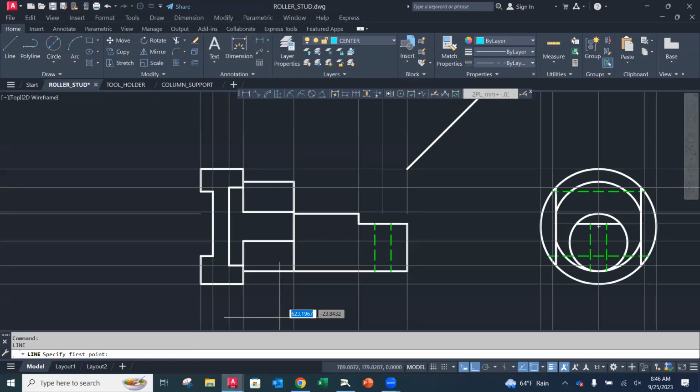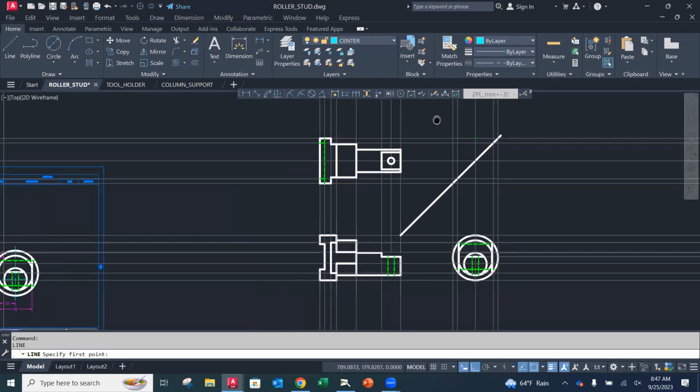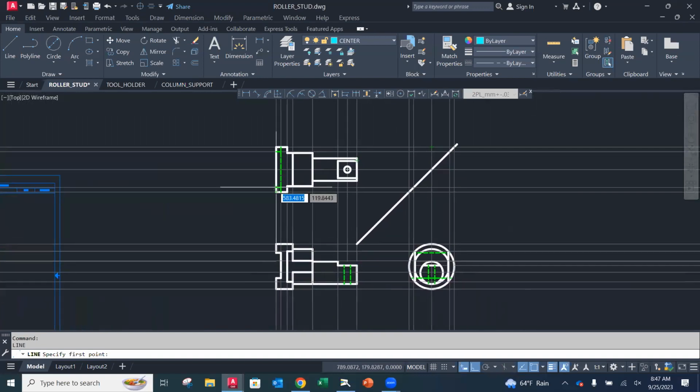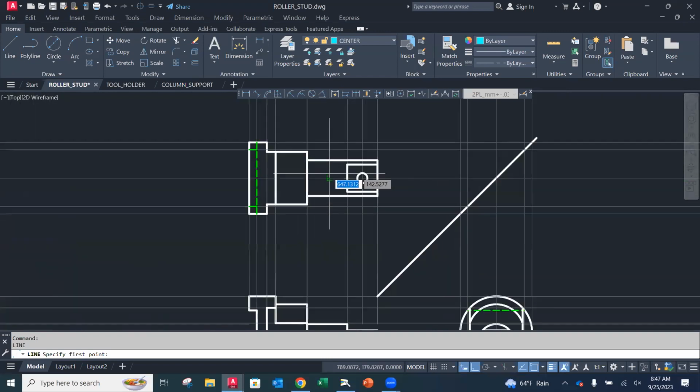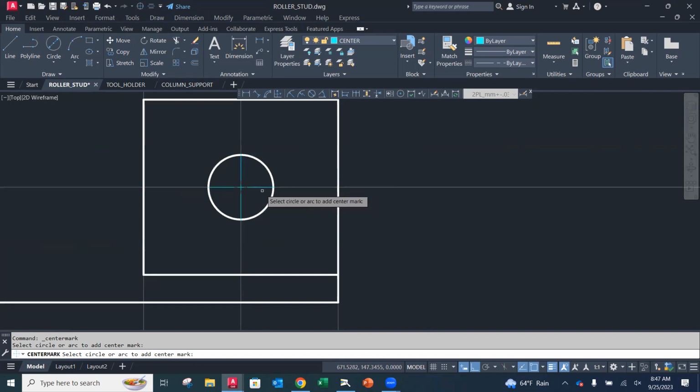All right. So now that we have the construction done, like I said, center lines, I'm going to let you guys put those in. Does that sound okay? Go ahead. Whenever an arrow is dealing with the center mark, it doesn't extend past the circle mark. I think there's a problem with the scale of it. Could be, and I tried messing around with that. I'm not sure what to do, but let's say we're on our center line and we do the center mark, we put it in place, and it doesn't go much beyond. All you need to do is grab it and go a little bit over.